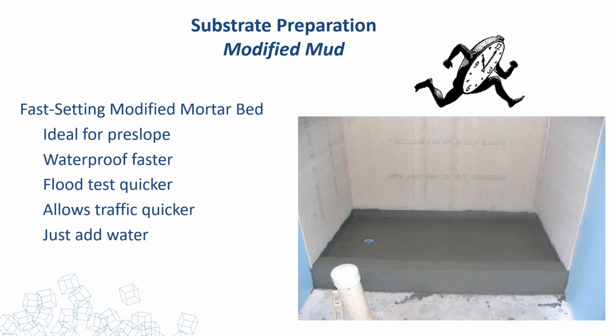Today, it's fairly common to have fast setting mortar beds, really primarily for shower pans. I'm not aware of them really being used many other places, but they're ideal if you want to go in and create a pre-slope before a pan. You can get in there typically with waterproofing much faster. You can flood test the overall installation much quicker, allow traffic faster. Just add water and go.